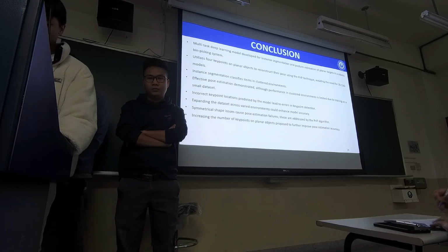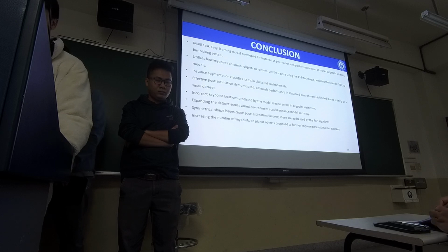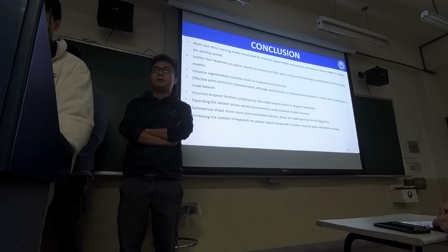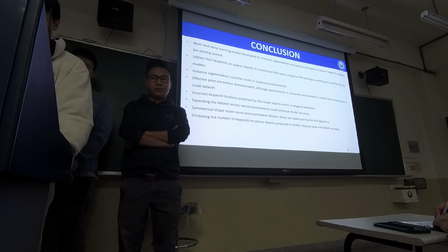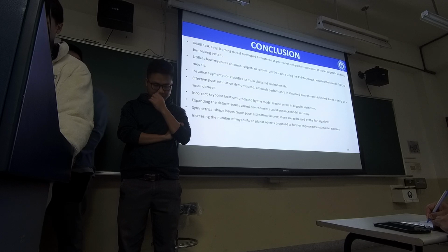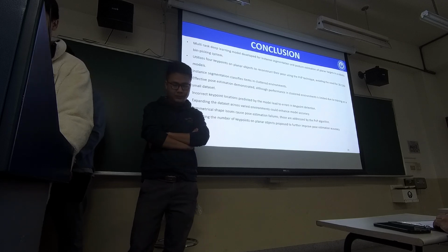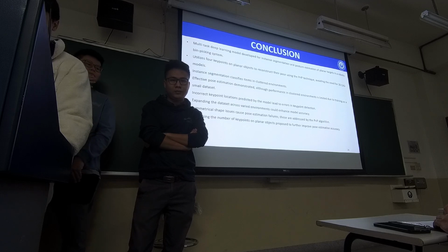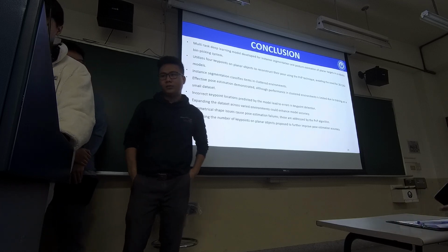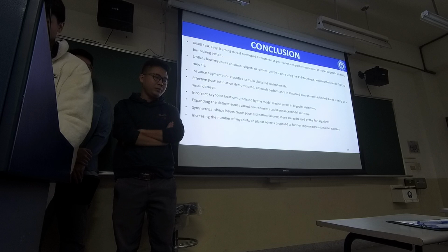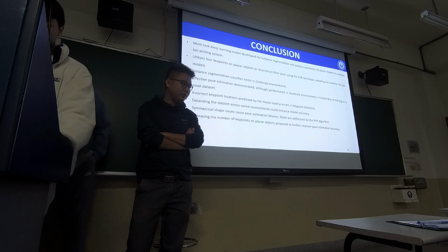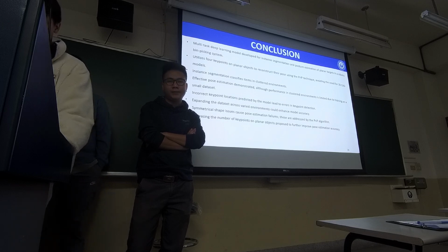Our model efficiently classified objects in cluttered environments through instance segmentation and demonstrated accurate pose estimation. However, we observed certain challenges, such as errors in key point prediction and limitations caused by training on a small data set. To address these, extending the data set across varied environments will further enhance the model's robustness and accuracy. Additionally, symmetrical shapes presented pose estimation failures, which were mitigated using a PnP algorithm.